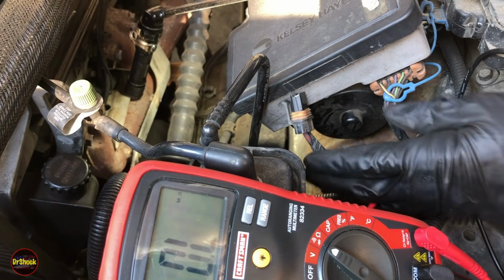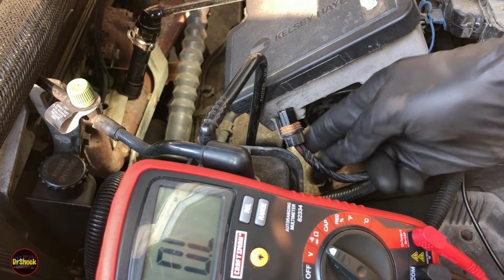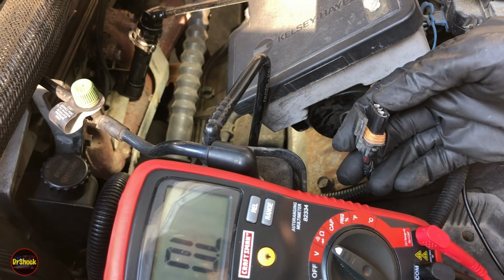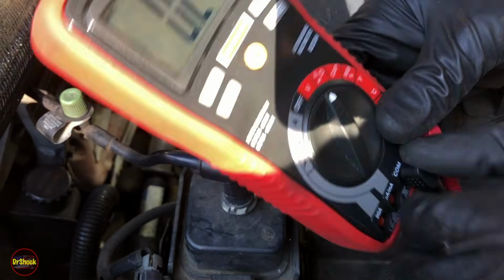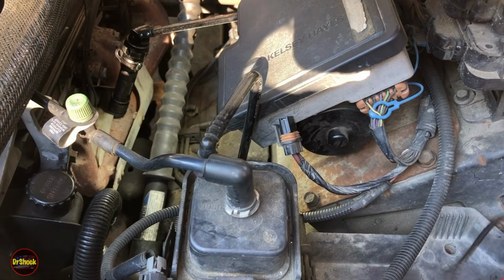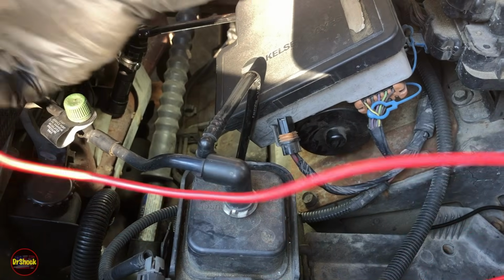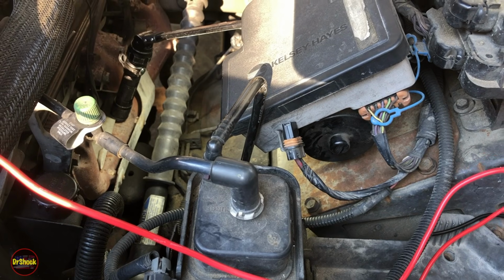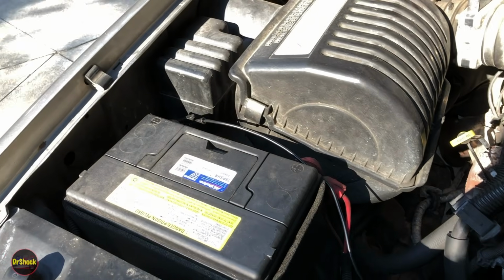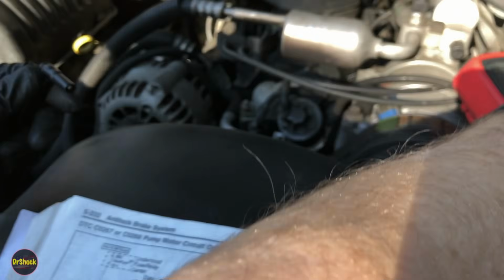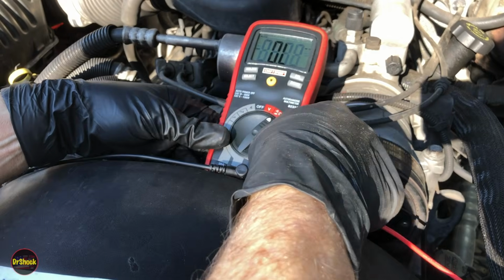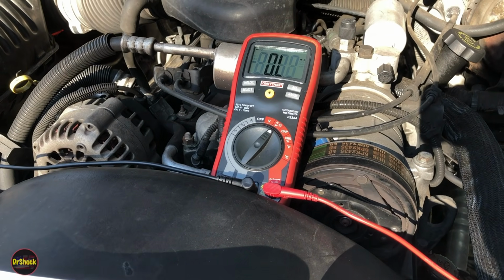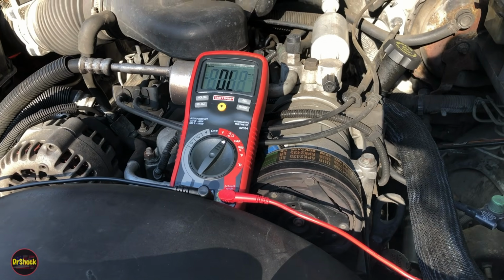Pull it up. And now what we're going to do is measure the resistance from the negative terminal of this connector over to a ground. And the best ground I can think of for this test is just to take it straight from the battery. So we're going to unplug this particular type of connector that we had. And you can see what I've got here is a different meter connector where I've got an alligator clip right on the negative terminal of the battery. And we're just going to plug this guy into our meter. Set him up here. And then we're going to make that measurement and see what we get.